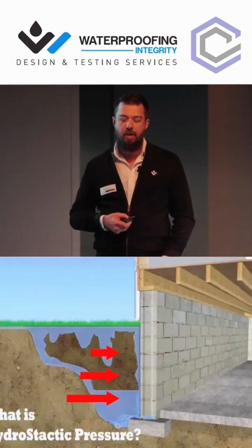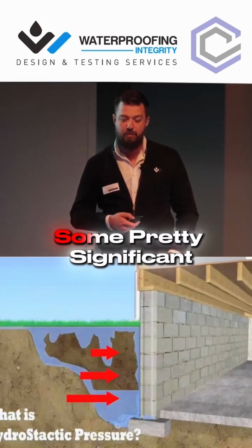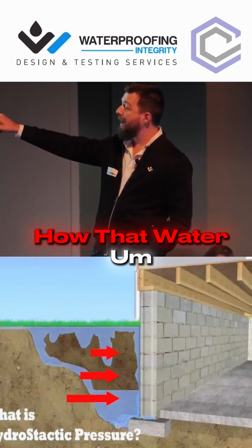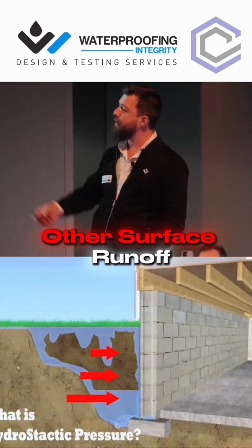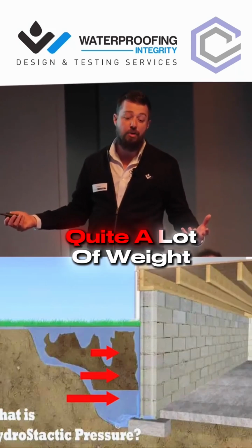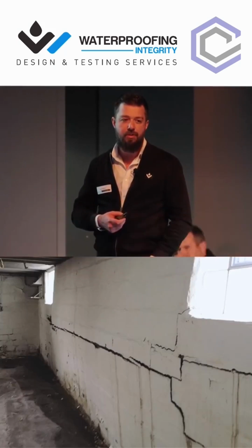Probably a term that a lot of you are familiar with. It's the reason why basements leak most of the time, and it can cause some pretty significant issues on a building. Nice simple diagram here shows how that water, in this case from ground level, presumably rain or other surface runoff, has infiltrated down and is starting to build up. And water has weight, quite a lot of weight in fact. And when you allow it to bear against a structure, you start to get these sort of issues.